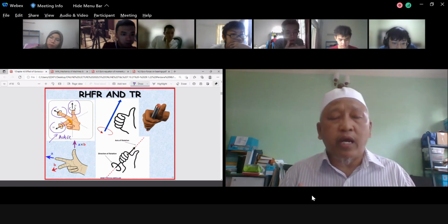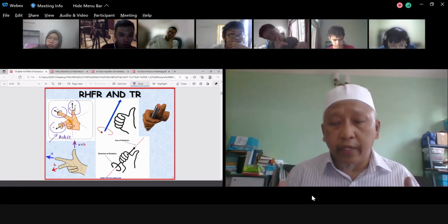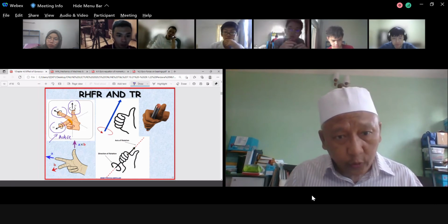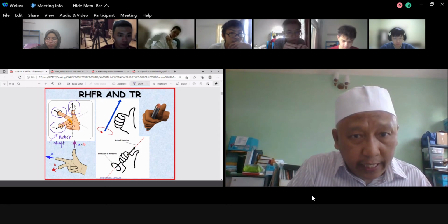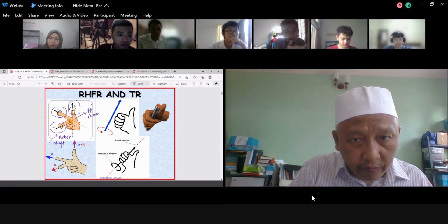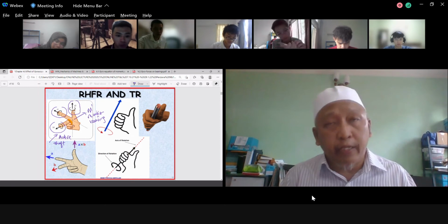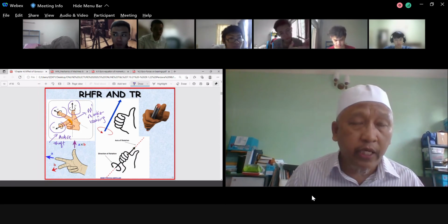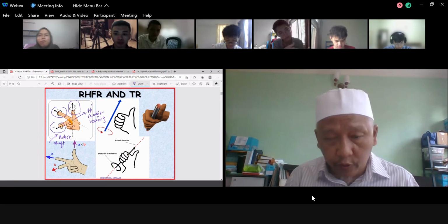So if the question is asking about, for example, a shaft carried by a bearing, this one will be on the shaft. So on the bearing it will be in the other direction. This one will be M prime, which is the reaction in the bearing. If it's not a bearing, it could be a pin, for example. It could be a bracket. It could also be a coupling, for example, so on and so forth. Universal couplings, yeah.